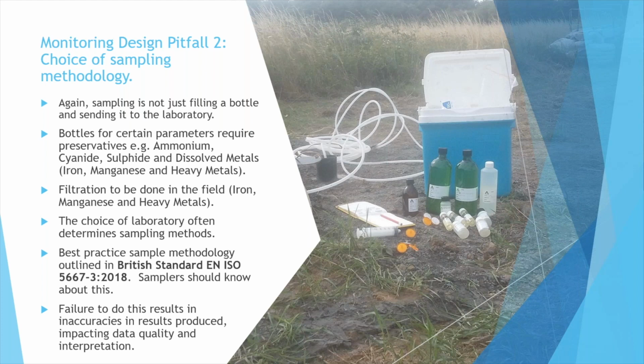If you're looking at dissolved metals and heavy metals, then you also need to do filtration in the field, so that your dissolved metal sample is an accurate reflection of the concentration of dissolved metals within the sample bottle. The reason for doing this is that there are two potential inaccuracies that can occur if you don't do preservation and filtration of dissolved metals in the field. One is that chemical reactions, precipitation of the minerals, or adsorption of the metals to the inside of the bottle can occur in transit. A second is the potential for another inaccuracy due to the order in which the acid is added at the laboratory versus the filtration, and I'll come on to that in a case study in a minute.